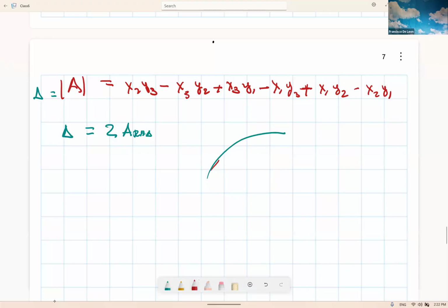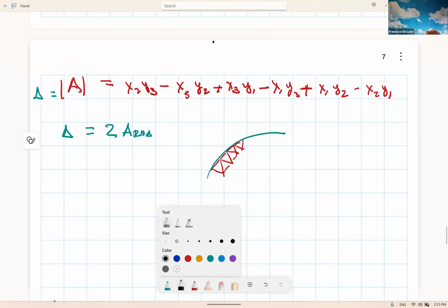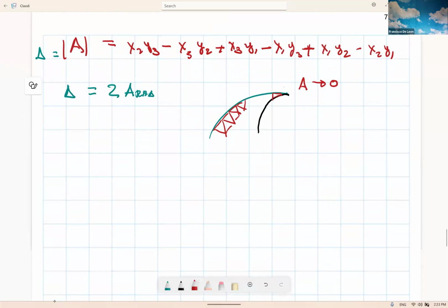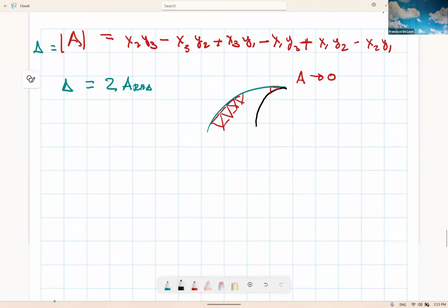So if you can form this with good triangles, it's fine. But as I just mentioned, if you have another element of this that goes like that, at this point, you may not have good triangles. If you need to go very fine, very fine, very fine, the area of this triangle is going to tend to 0. Because we're going to divide everything by the area of the triangle, when you divide by a small area, you magnify the errors and the problems and the convergence, and everything becomes complicated when these triangles don't have a reasonable area. All right. So in the end, I am just going to write the values of my calculations.